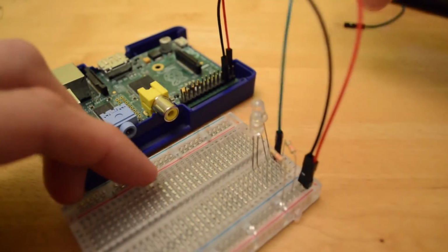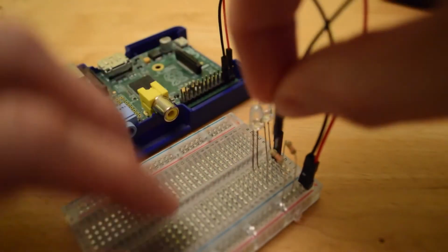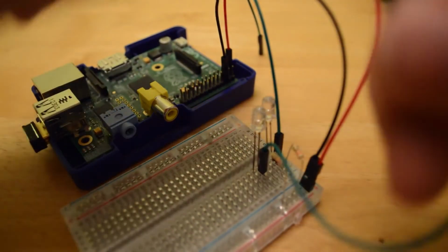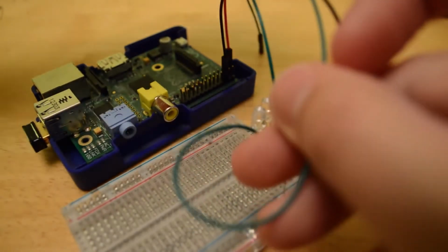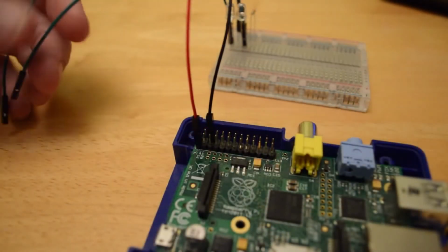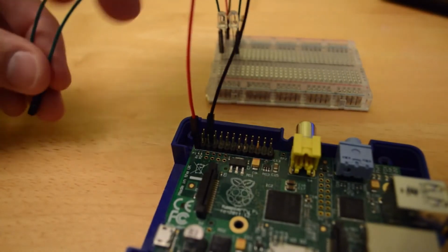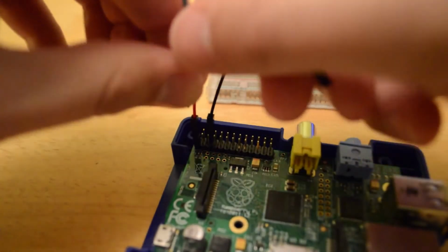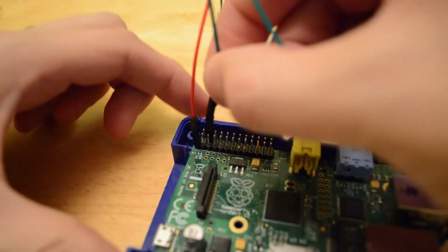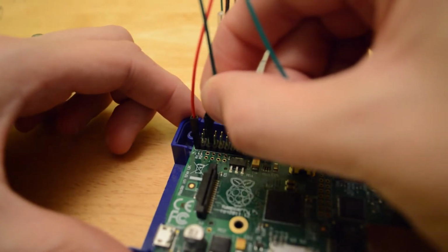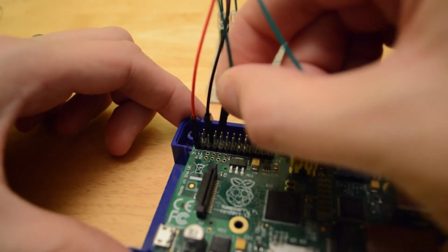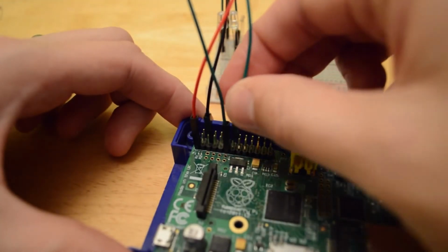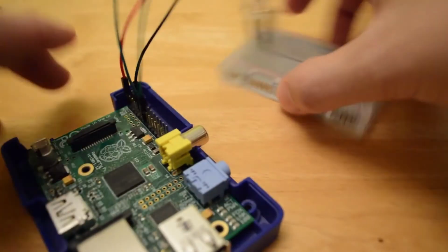All we have to do now is just connect up the positive leg on both of those to our GPIOs, pins 17 and 27. And you notice that it's a male connector goes into the breadboard, and it's a female connector that goes into the Raspberry Pi. So I spent a little bit more time on this video actually showing you how to plug things in, because obviously it's a bit fiddly the first time. So we're going to count down based on the diagram you should have in front of you, and we're going to plug our pins in. So that's pin 17, and that one next to it's pin 27.